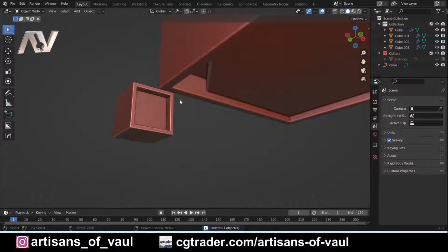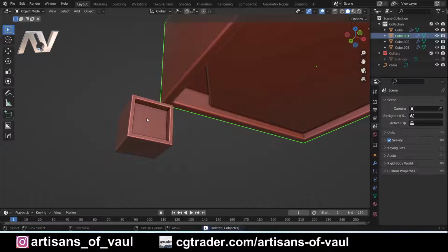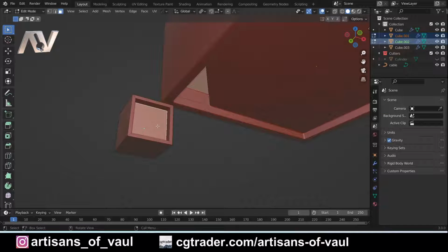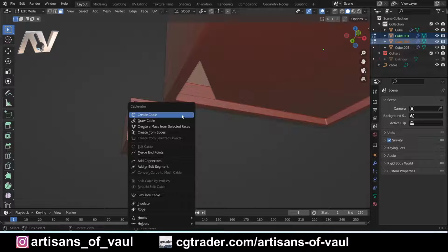I mean, essentially you can do that and it's perfectly fine. But, and this is amazing, I'm going to select both objects, tab in to face mode, and you can see I've been playing around with this already. I'm going to select the two faces I want the cables to go in. Now this is really important that you've tabbed into face mode. If you don't have machine tools, tab and then 3 or the button up there, but those must be selected.